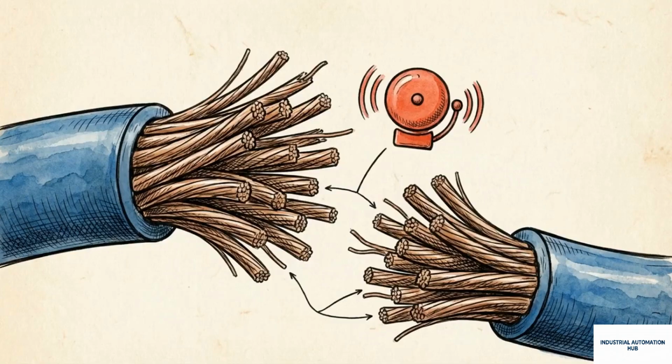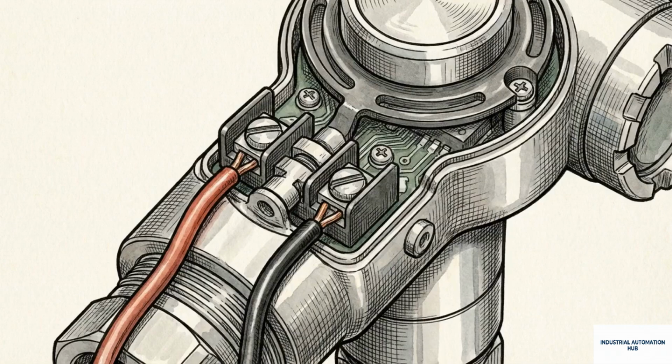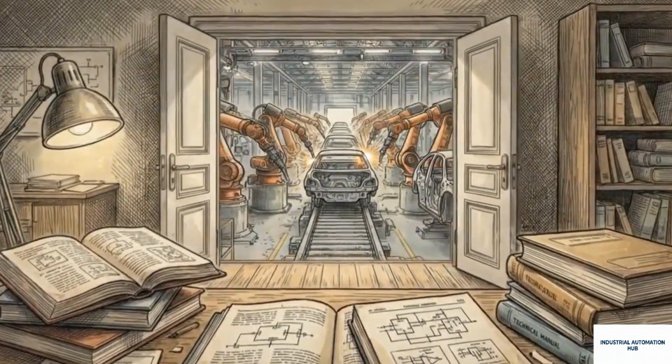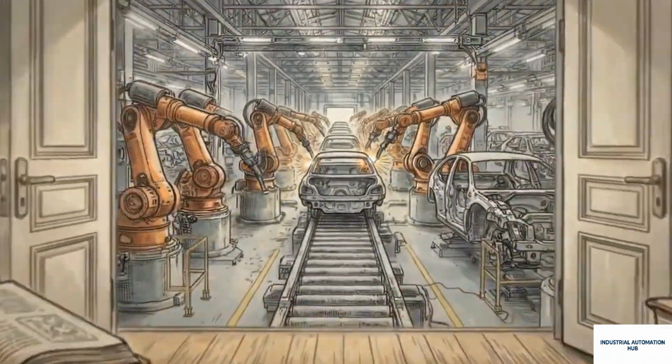Second, the 4 milliampere baseline creates a live 0 for immediate wire break detection. This checklist highlights our third point. Loop power allows for highly efficient, cost-saving 2-wire setups. Explaining these three concepts clearly is what separates a classroom education from the demands of a working plant.